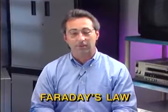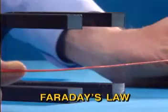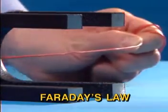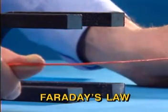These 4 factors are related to a basic law of electromagnetic induction, known as Faraday's law. This law states that the voltage induced in a conductor is directly proportional to the speed at which the conductor cuts the magnetic lines of force. This law is the basis for the design of the electric generators in use today. Let's take a closer look at how a generator works.